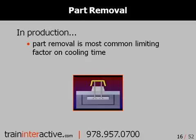In reality, using a stripper ring or stripper plate would be the best way to eject this part, as it will allow us to locate adequate water lines very evenly so that now we can distribute ejection forces evenly across the perimeter of the part.